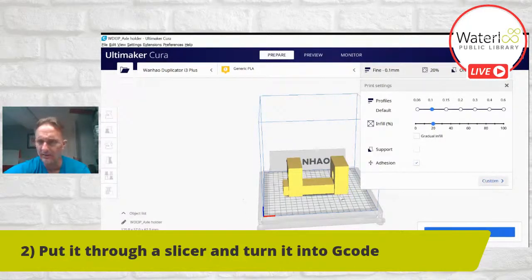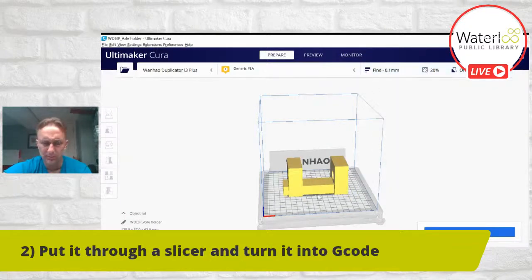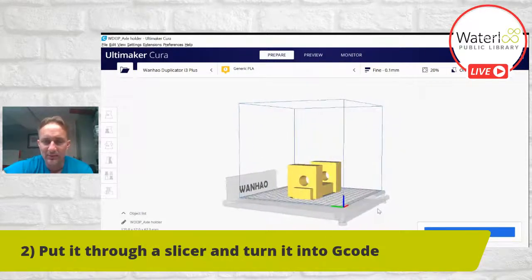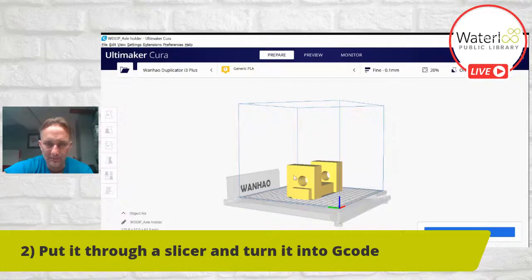So on my axle holder here, in the circles, these holes have no support. Now, because it's a circle, as the 3D printer prints, it prints up layers at a time from the bottom up, really thin layers. It could probably build enough support with the circle as it builds up one layer at a time that you don't need to worry about support.